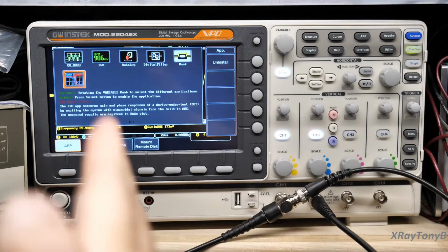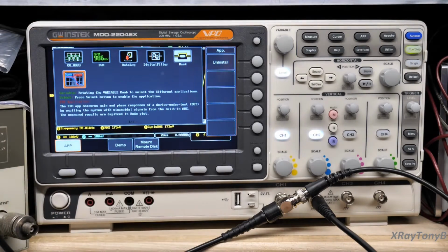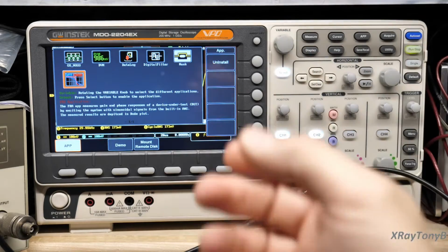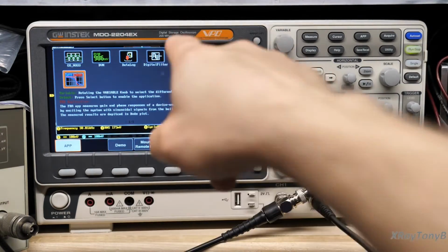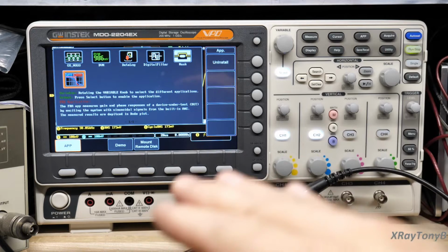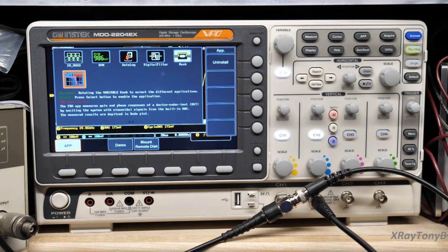So if we put a set amount of amplitude into the input jack, so we connect the signal generator of this device into the auxiliary input of an amplifier, for instance, and then we measure the signal coming out of the speaker terminals, let's say, you can actually see if the gain between the input and the output changes with frequency.